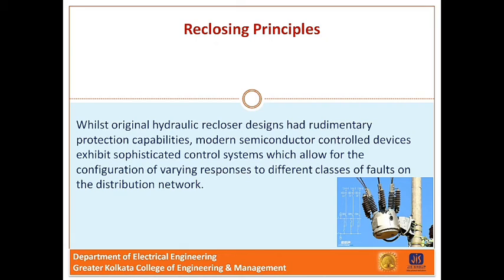Whilst original hydraulic recloser designs had rudimentary protection capabilities, modern semiconductor control devices exhibit sophisticated control systems which allow for the configuration of varying responses to different classes of faults on the distribution network. The number of reclose attempts is limited to a maximum of 4 by recloser standards. The basic philosophy of reclosing is to actively consider the fault cases and provide an effective response based on the fault type. This is done on a probabilistic methodology in conjunction with the detection of fault type.